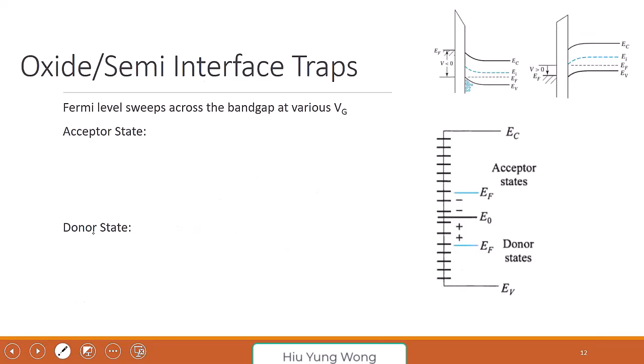It's about the interface trap I just told you. So at the interface, there's something called a trap. What is a trap? Just think about it in English, it's a trap. You trap the animal, trap something. But here it traps the carrier. It can trap the electron or trap the hole. If it traps the electron, it cannot move, but it contributes to the charge. So as you can say, if I trap more electrons, you need to increase the threshold voltage because you have fewer electrons, right?